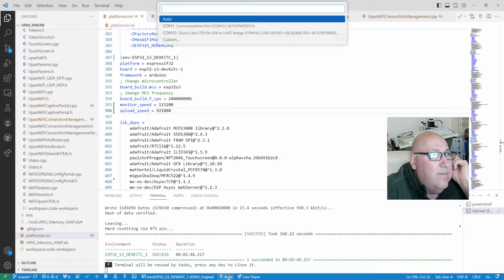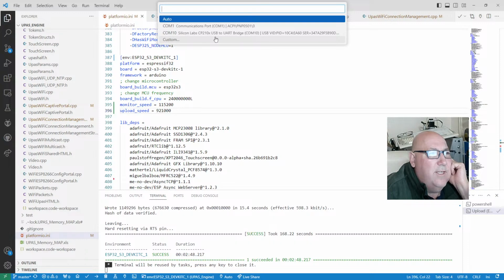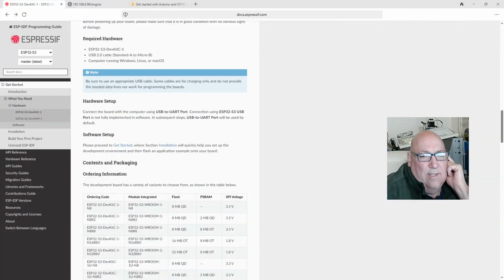See this one here? See, it says Silicon Labs CP210X. That's the UART. That's the chip between the UART connector and the ESP. Now, if you go through to the USB, as detailed down here on this one, the ESP32's doing the USB directly without a chip. So it's trying its best, but yeah.